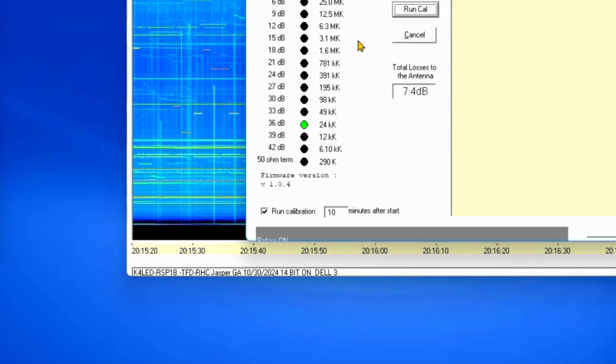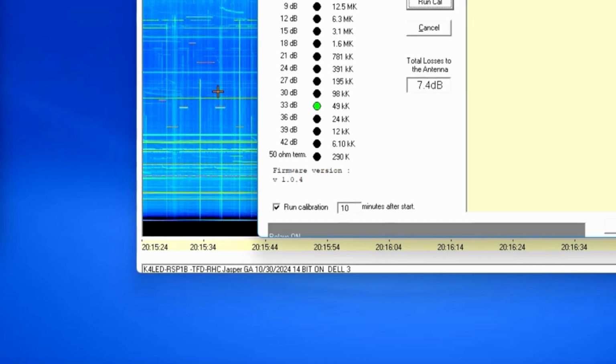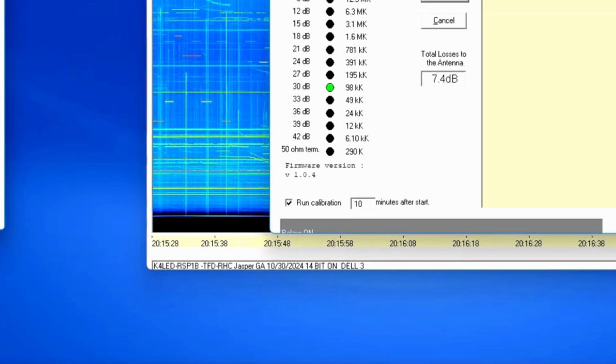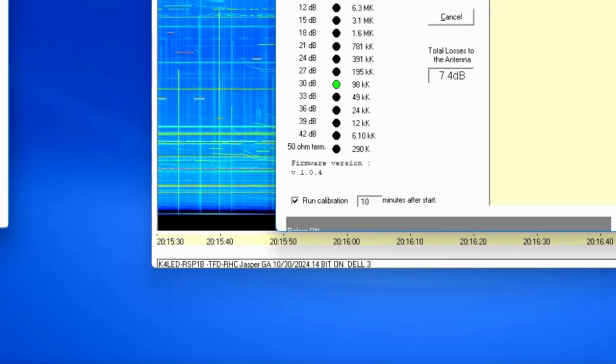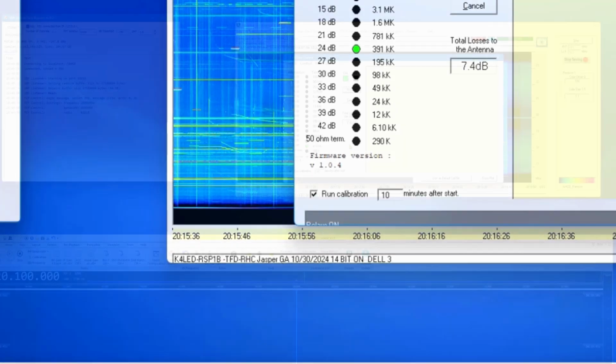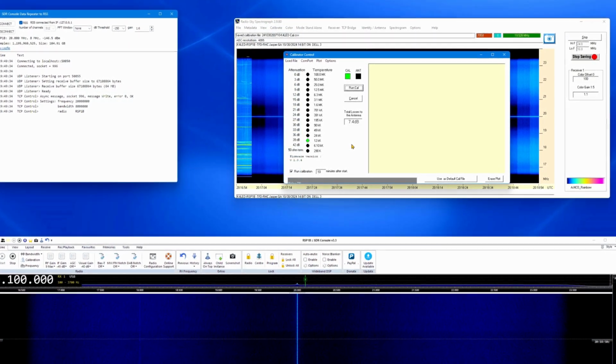While setting the dynamic range plot, ignore the RSS spectrograph. These settings affect your saved .sps calibrated files, so do not change them once an excellent dynamic range plot is obtained. If you need to change them, rerun the entire calibration procedure.